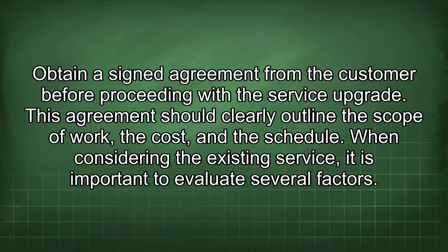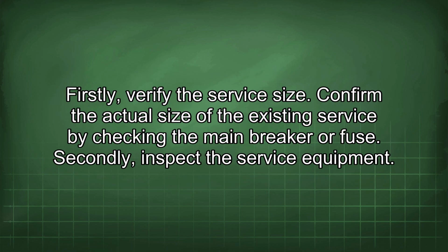When considering the existing service, it is important to evaluate several factors. Firstly, verify the service size. Confirm the actual size of the existing service by checking the main breaker or fuse.